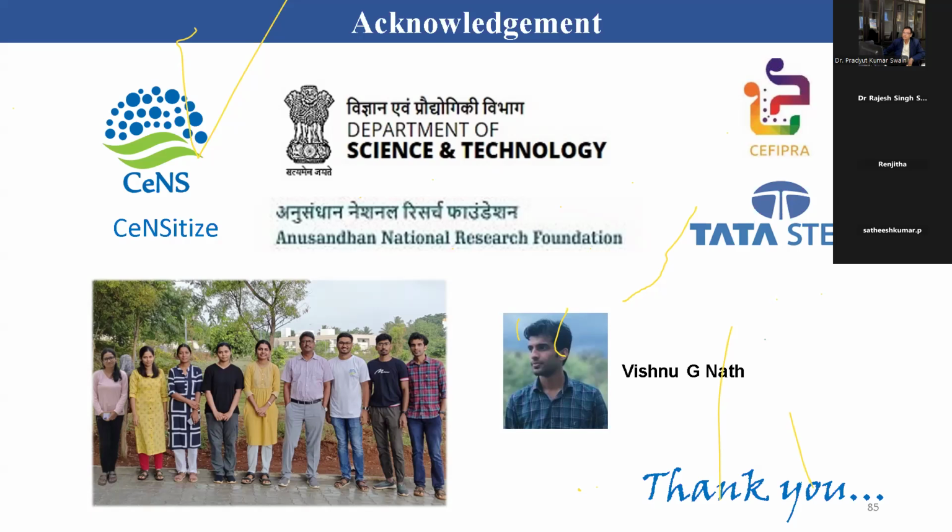Sir, in chat, Bhuihh is asking, could you please explain the fabrication method of the interdigitated patterns, whether photolithography technique was used or any other method? Good question. This can be done by photolithography also. It depends on what dimension you want. Photolithography is needed when you are fabricating something in the micrometer length scale.